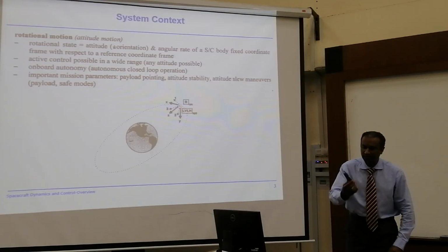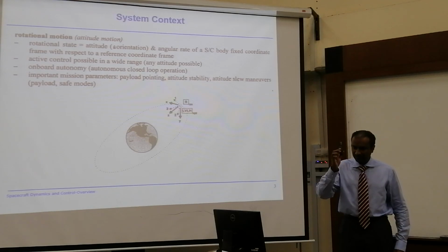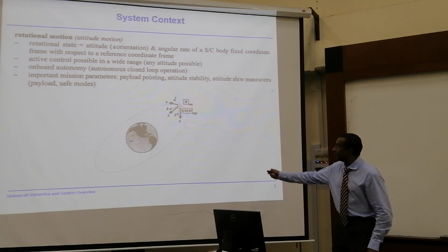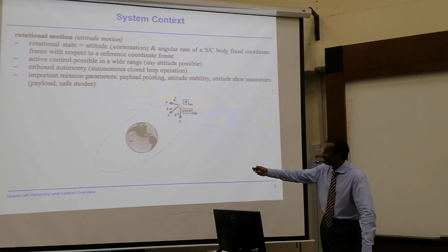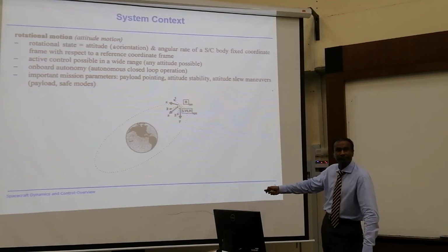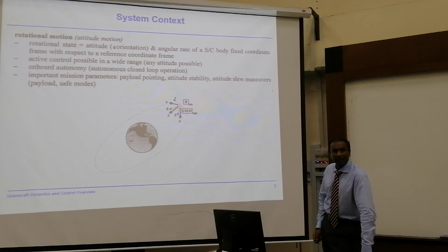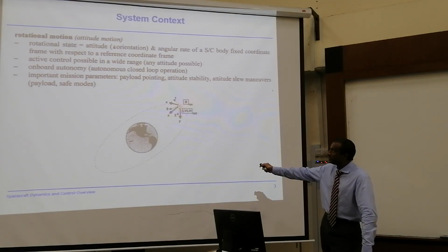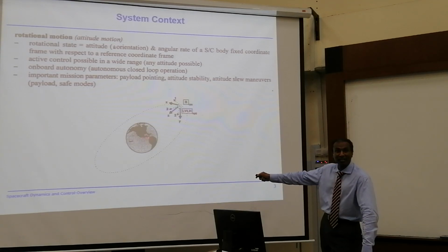I need to know what this is. Okay, we must have a coordinate here. I have this coordinate, and I must have a coordinate which is fixed here, which rotates throughout. Okay? Now, this particular coordinate in the attitude control system, we call it local vertical, local horizontal. The difference now, remember this. Remember that I told you there was another coordinate here, x, y, z, which is important to establish your position with respect to the geocentric coordinate system in orbital mechanics.